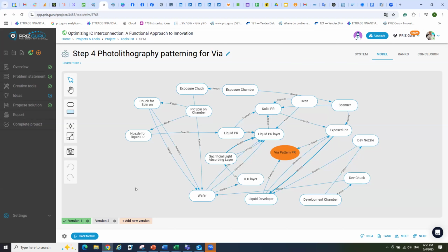Each time you took two parts and welded them together, you had to have fluorescent penetrant inspection, visual inspection, and a pressure test to make sure your weld was good. You had to have an x-ray. So if you could get rid of a weld between those two components, it was key, because you got rid of all the 4 or 5 different inspection methods that went along with that weld.